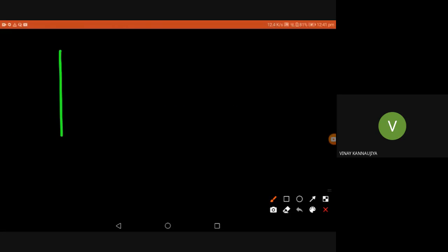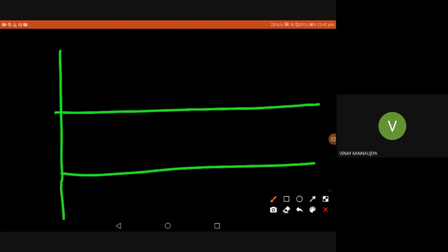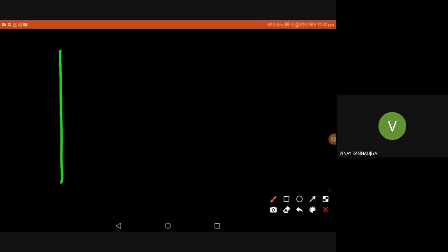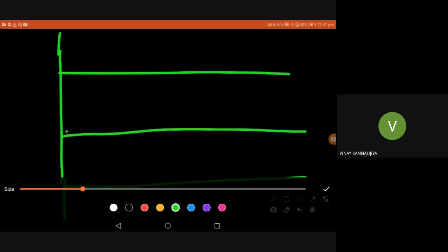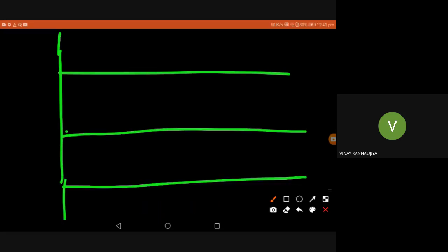Okay, so I'm going to plot VC with respect to the input. This is one minute, so I'll make it small. This is my input, this is my VC. Maybe I can plot the output also. This is the advantage of a simulator: if you have a simulator, you can just click any point and the simulator is going to show the value.